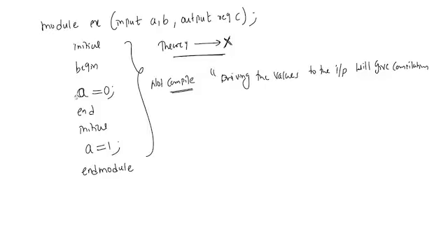So here you can use option C. C means it will execute, and A means it will not execute. Why? Because in C you are using blocking assignments, and you are driving the output, which is a reg. So I can drive the value to the output, but I can't drive the value to the input. So that is the reason.